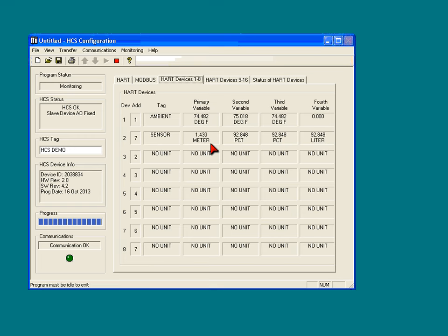And occasionally we get some customer calling and saying, hey, on my Modbus end, I'm reading 74.5 degrees Fahrenheit, but my HART instrument in the field is set up for degrees Celsius. How can you change them? We are not. That's a configuration problem that they have to resolve. We are not doing anything. We're just taking that 74.587 or 585 and putting it right into the Modbus registers to be read by the Modbus master.